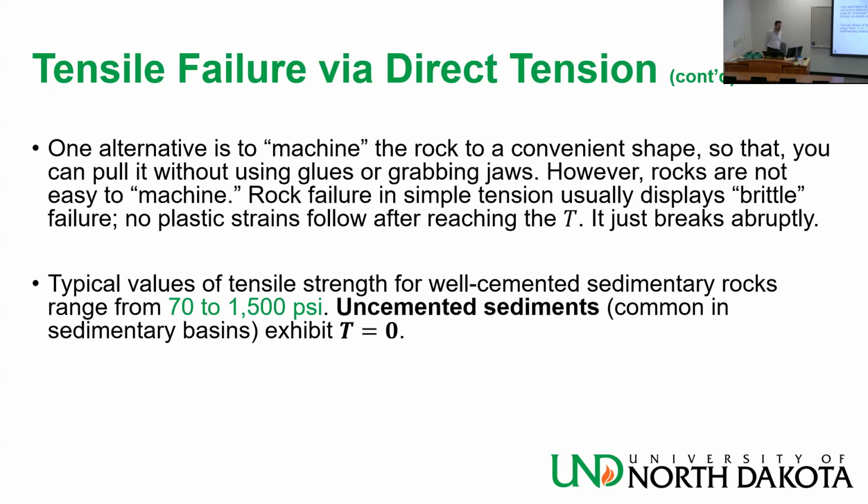Hydrostone cement, which is similar to Portland cement, is 700 PSI. The biggest value I have ever seen for tensile strength of rock under severe confinement, almost for shale actually, was from a Japanese paper I read from 2015. It said it was approaching 2000. That's crazy high. But this range is sort of what you expect, and I would say closer to 70 than 1500.